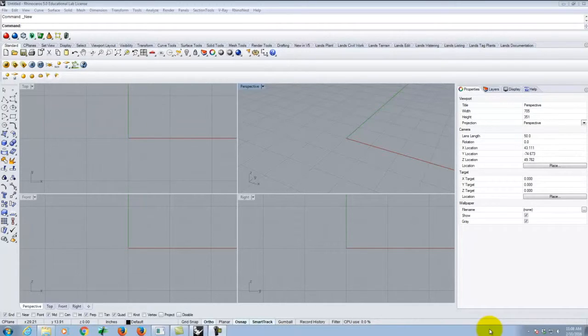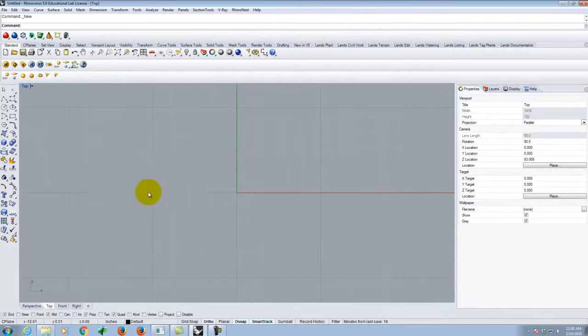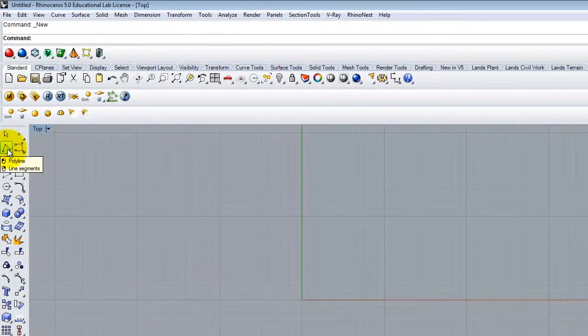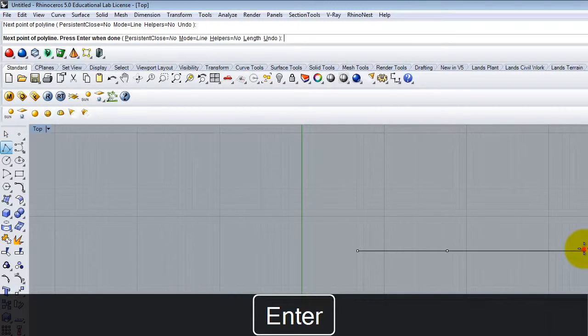Okay, so today we're going to start in the top view, as we've been doing, drawing a set of guidelines. And how you choose to draw this really is up to you. The little drawing on the side here says that we basically have a 2-inch radius arc, a 13-inch length piece, and then a 2-inch radius arc at the end. We have a couple different options for how we draw this. You could, for example, start with a polyline 13 inches long, and then you could draw an arc from the end.